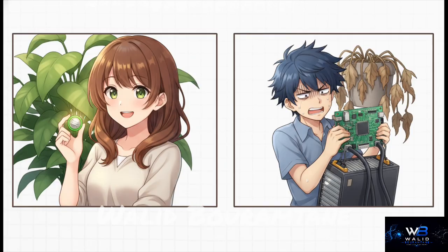In a practical application, say an environmental sensor waking up every 10 minutes, an STM32-based LoRa sensor will easily last 3 years on a standard CR2032 battery. If you put that exact same workload on an ESP32, it's completely dead in about 3 months.